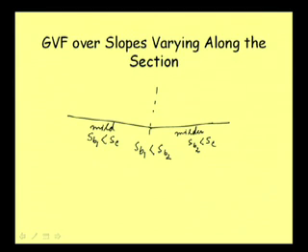Oh, am I wrong? Yes, I am wrong. SB1 is greater than or equal to SB2, because this is comparatively steeper than this one, but of course in the mild slope portion. Now, as far as supercritical depth is concerned, let us see what sort of profile it will be during the entire flow portion from here to here. So, as far as critical depth is concerned, YC, let us consider this as a rectangular channel.